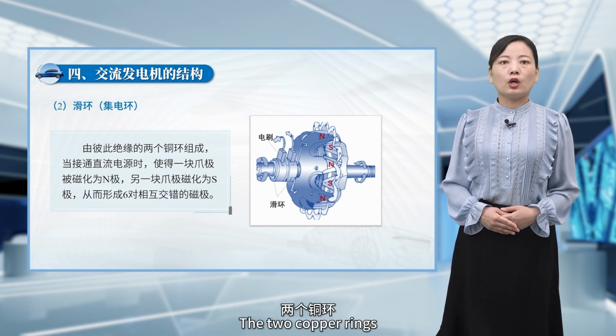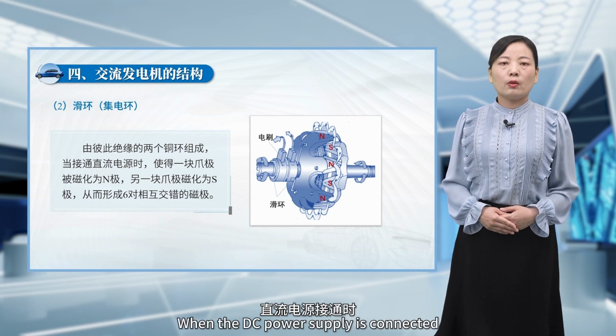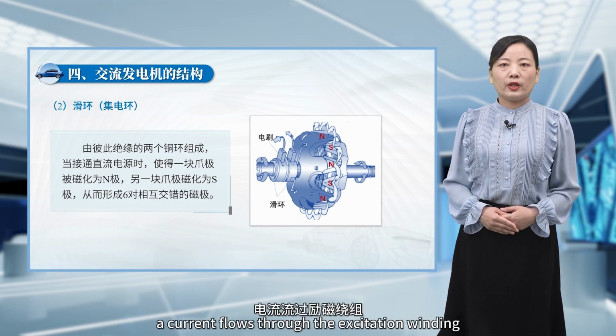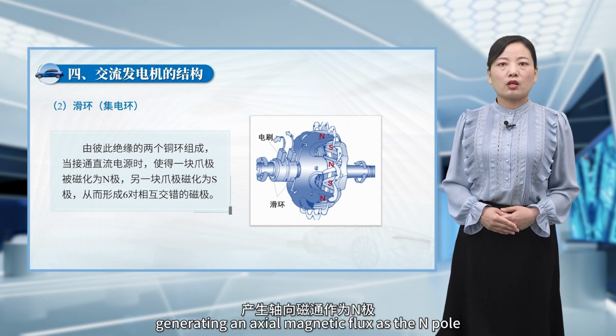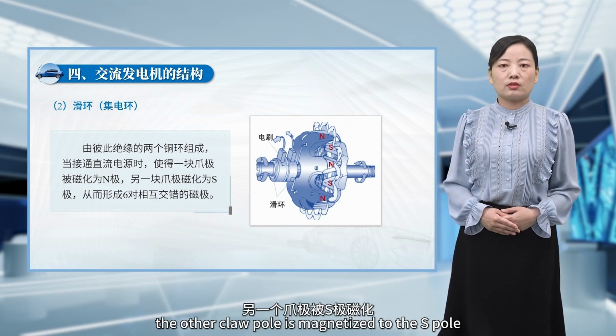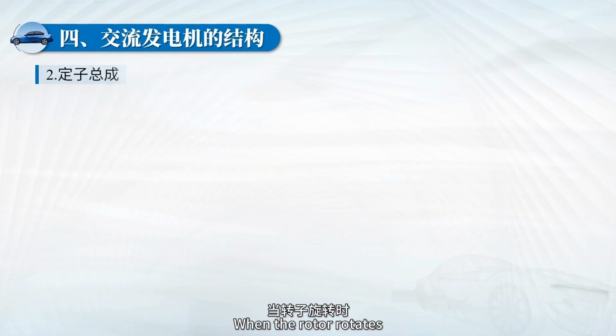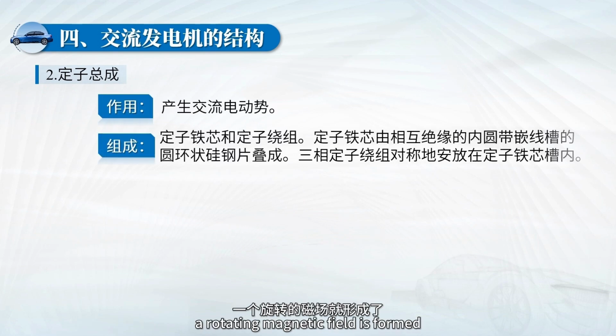The two copper rings contact the brushes of the generator. When the DC power supply is connected, a current flows through the excitation winding, generating an axial magnetic flux as the N pole and the other claw pole is magnetized to the S pole, forming 6 pairs of interlaced magnetic poles. When the rotor rotates, a rotating magnetic field is formed.